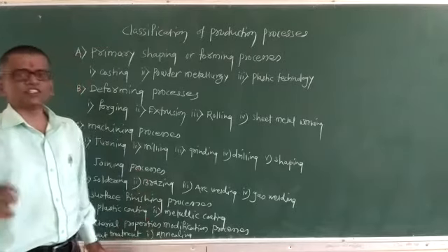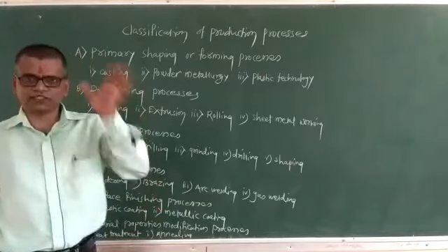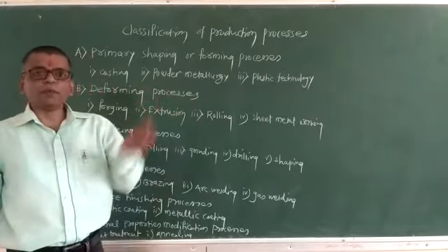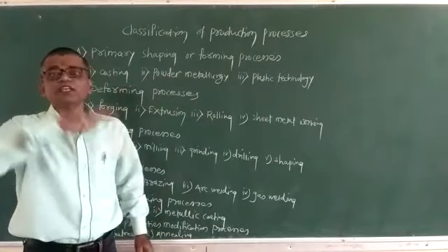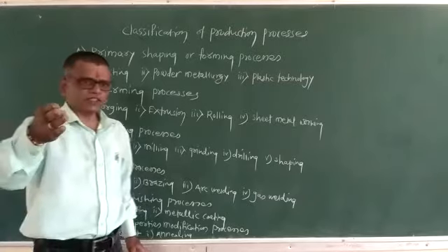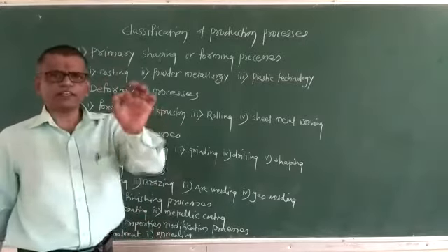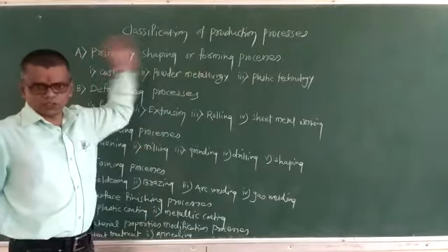That stage is called the pre-sintering operation. Then the sintering operation is carried out in a furnace. The object is heated up to the melting point of the base metal. After that, the object becomes extremely hard. And then the last one is the secondary operations, that is, finishing operations that are carried out on the desired product. So that is regarding the powder metallurgy process.